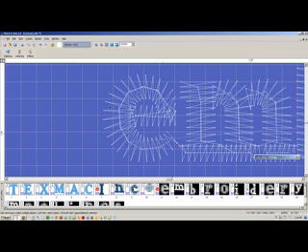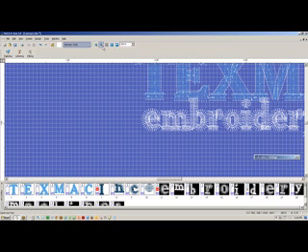So it's okay back and forth, but one thing in small lettering is you want to pay attention to the negative space inside loops, like the inside of this lowercase e, the inside of the M's here. We're also making a lot of holes here. So what's going to happen is this is probably going to collapse. So this font is a no-go. Even though it's wide enough, a lot of the inner spaces are going to close up.